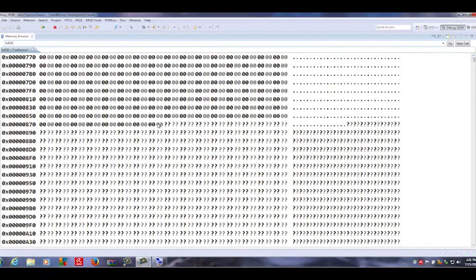And if we declare a variable to be char, it's only going to use 1 byte. If we declare a variable to be integer, it's going to make it 2 bytes. If we declare a variable to be long, it's going to make it 4 bytes. Now RAM, as we said, starts off with random information inside here, and if you're declaring a variable, that's fine, but it does not put a default value in there for you. So one of the things you have to do is initialize the variable, whether it's char, integer, or long, because if you don't, you're going to have a random value there, and it's going to make your program do weird and wonderful things. So this is pretty much everything that we need to know now to finish off lab number 2.